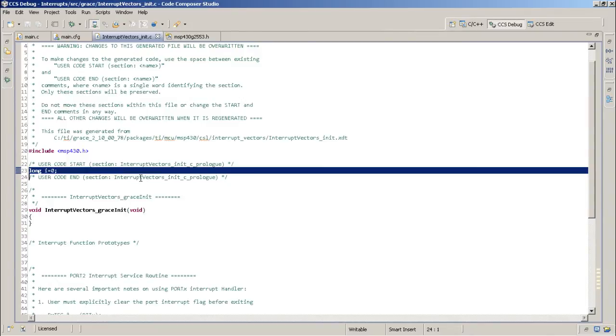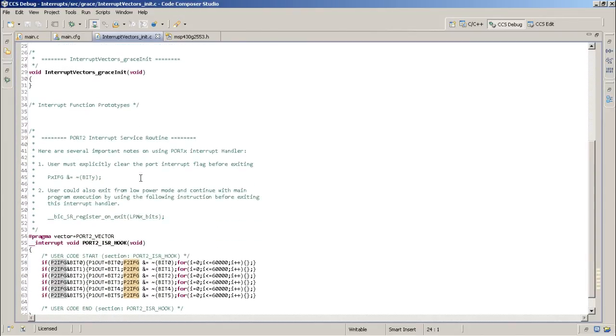I have declared a long variable I. Long, it is 16-bit. The registers of MSP430 G2553 are 16-bit. They can be used as 8-bit, but I am using a long so that the delay I can produce is more. The maximum count of I is 0FFFFH, 64K approximately.